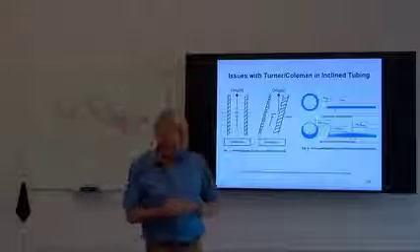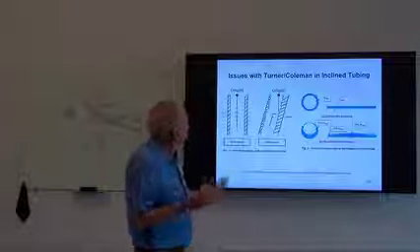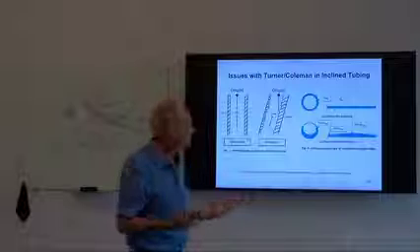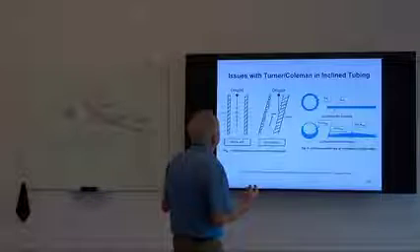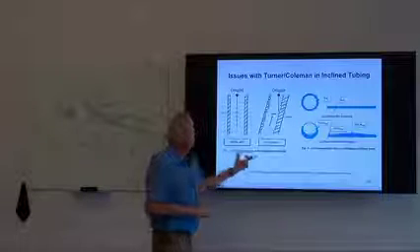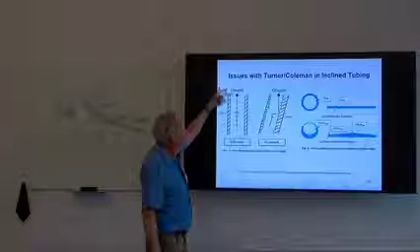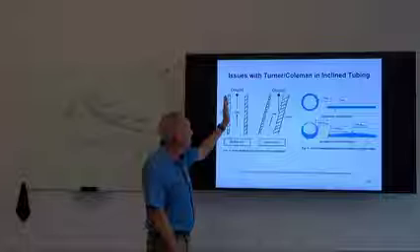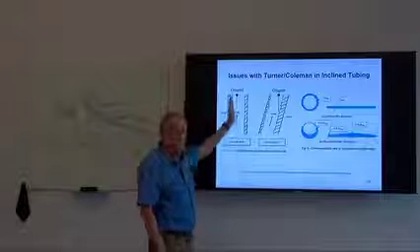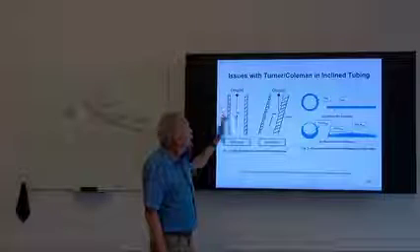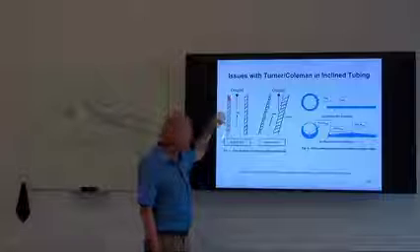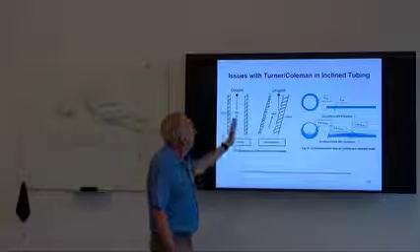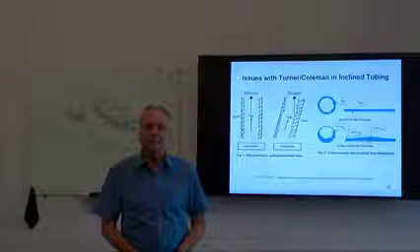So in inclined tubing, why would we have a problem with Turner? Well, it comes from the fact that Turner and Coleman are based on droplets falling against a gas flow in a vertical well. And so we're trying to keep this droplet suspended. It's trying to fall vertically. Our gas is flowing in line with our...